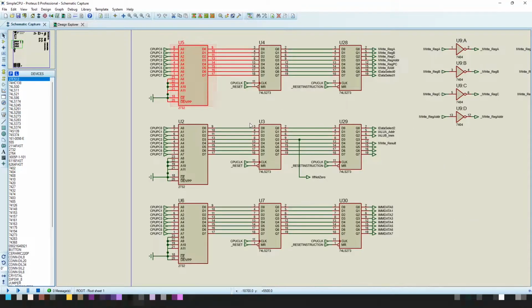Now, we're going to go to the real assembly code in a minute, and I'm going to show you what that looks like. But basically, each instruction for this simple CPU has about 24 bits, minus about 3 actually. We have 8 bits here for writing the registers A, B, and C, and the address register, and the program counter signal here and the RAM. We also have the first 2 bits from data select, and the 3rd bit for the data select coming into the 2nd byte.